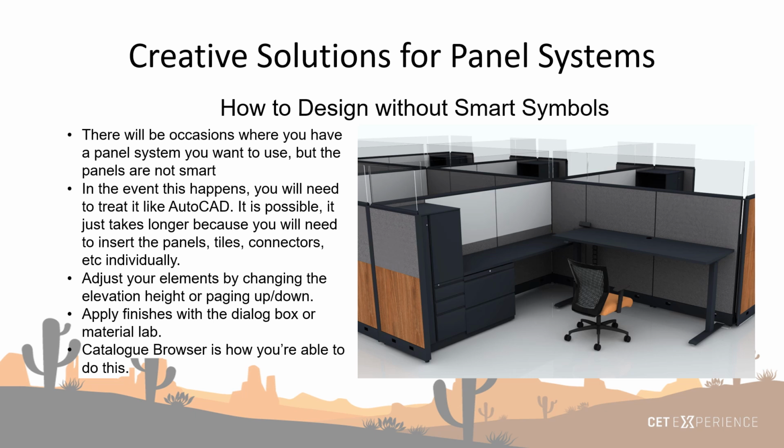Just real quick, I would like to cover how to design without smart symbols. There will be occasions where you have a panel system that you want to use, but the panels are not smart. If something like this occurs, you would need to treat it more like AutoCAD. It's possible, just know that it's going to take longer because you will need to insert all of your panels and your tiles and connectors and everything else individually, right?